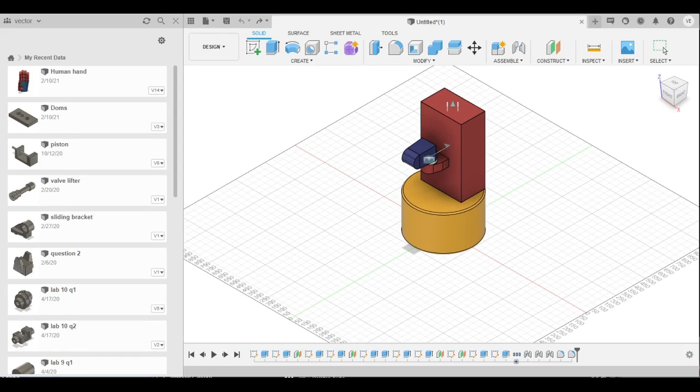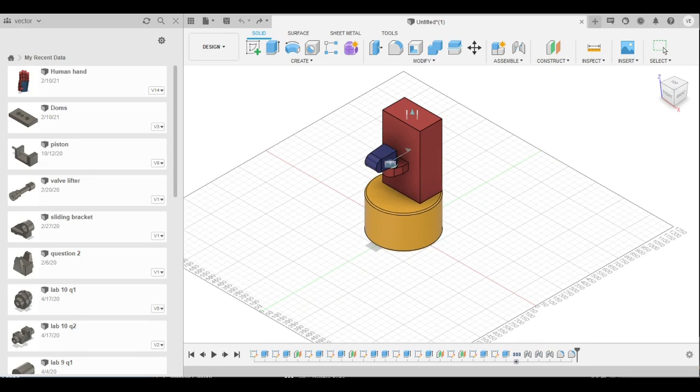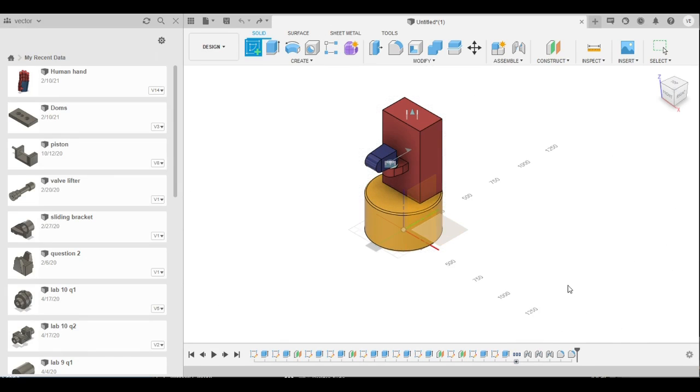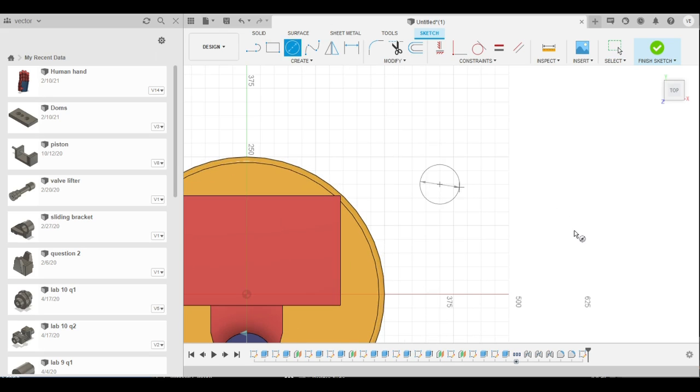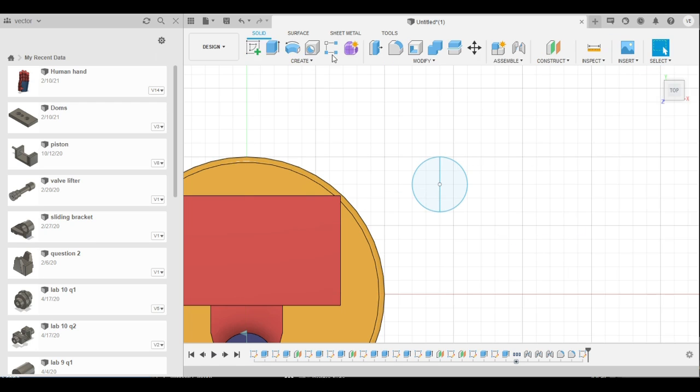Hi guys, as Joshika has completed the part of explaining the joints and the degrees of freedom of the system, I'll be continuing by making the joints of the hand. Okay, so first let's make a semicircle of radius 50. So this part is a semicircle. These are two semicircles. So I'm going to extrude half of it to a height of 120 mm.